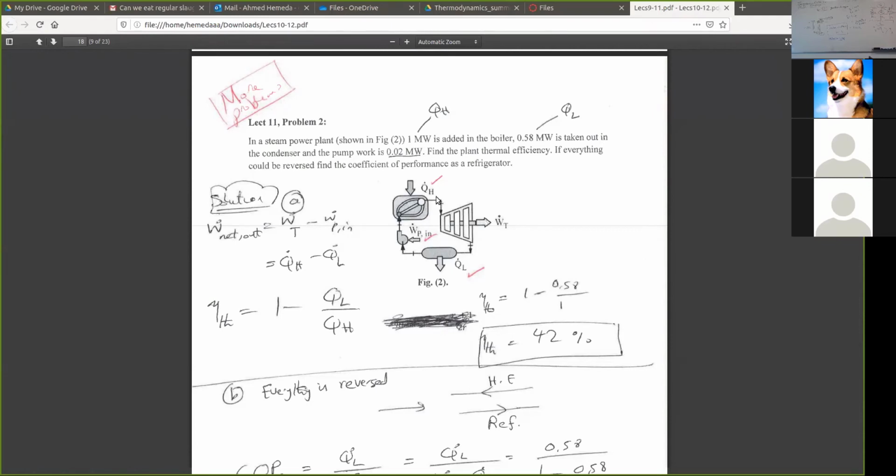So, first law of thermodynamics, open system, for a boiler, turbine, compressor, pump, condenser, anything you can apply between state 1 before the boiler and state 2 after the boiler. This is before the boiler here, after the boiler there. So energy increases. Coming inside with high pressure but low temperature, going out with the same high pressure but very high temperature. Make sense?